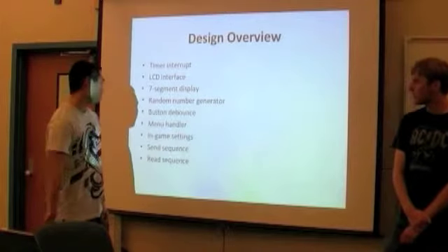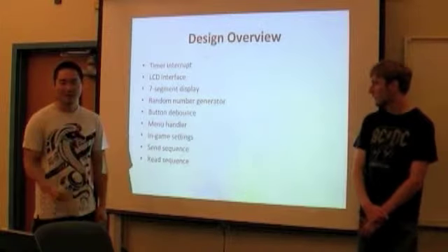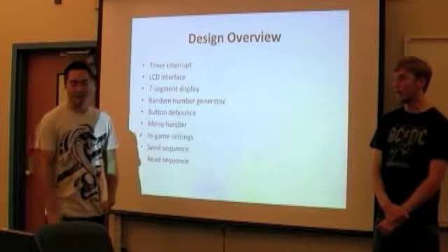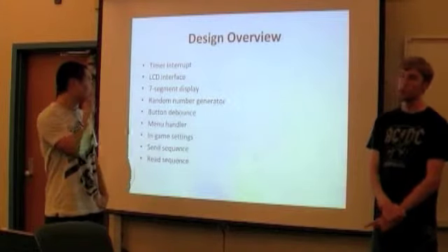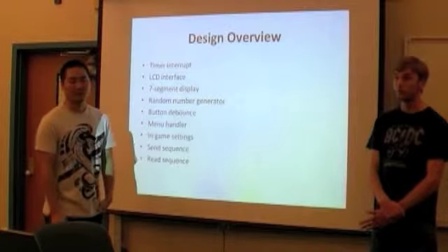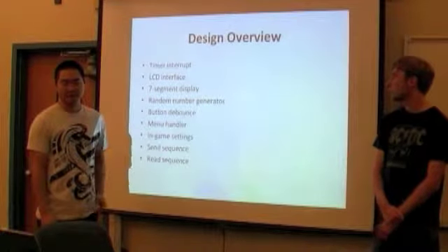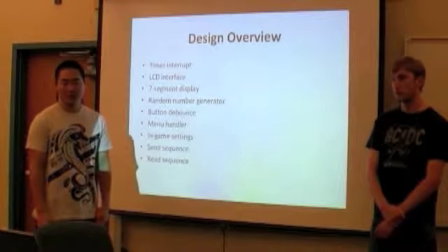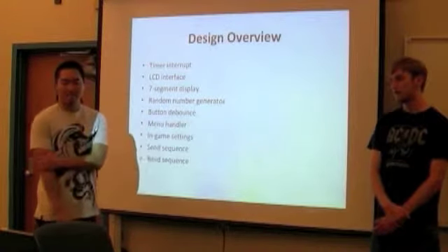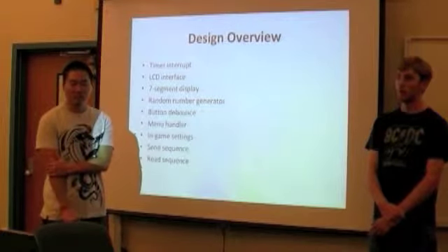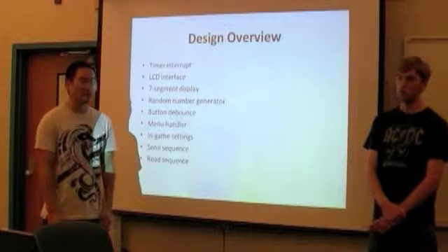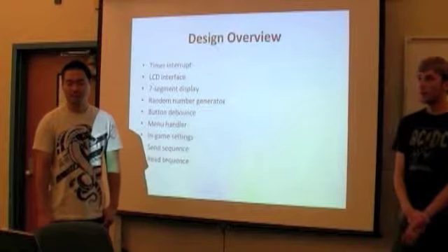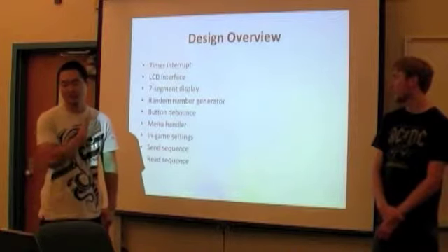So these are the basic functions and modular design we had. We had the timer interrupt, which we used to time the user input and to produce the different notes using a sine wave. And then the LCD interface, we reused some code from previous projects. We did have to make some changes so we could write to both lines individually, the top line or the bottom line.